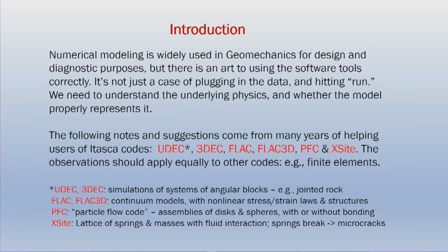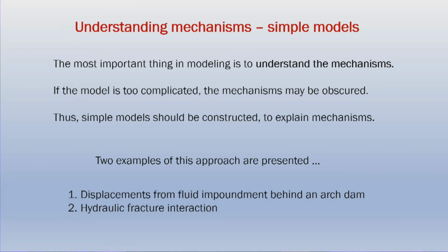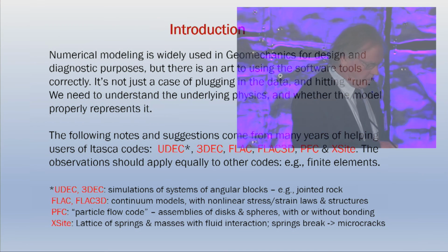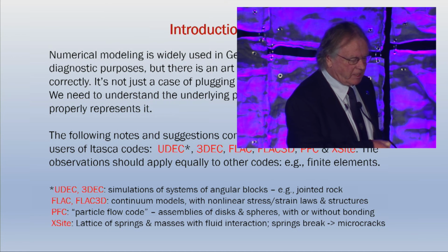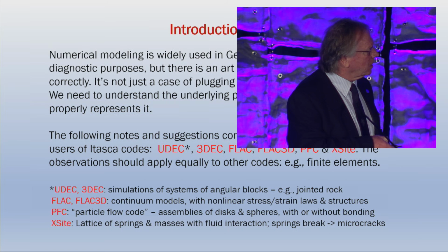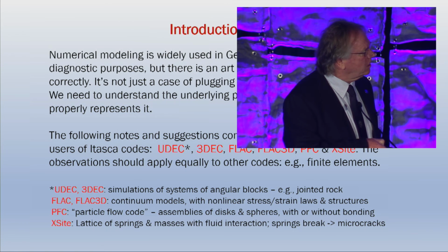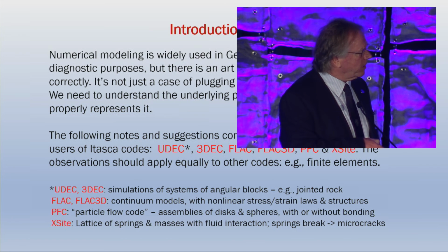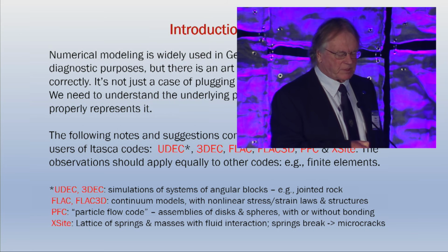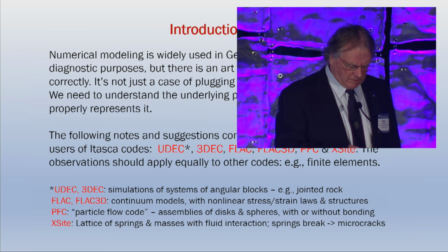The notes in this paper come from many years, probably 15, 20 years, of helping users with Itasca codes. These are the following codes. And just for those of you who are not familiar with these codes, UDEC and 3DEC simulate systems of angular blocks, like jointed rock. FLAC is a continuum model with nonlinear stress strain laws. PFC is a particle flow code which models spheres and disks. And XSite is a lattice code. All these codes are coupled with fluid flow.